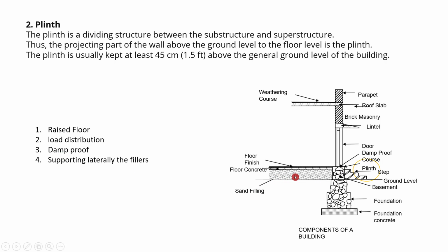It means I can have the fillers here. I told you it can be sand filling or any building waste, whatever the contractor or the builder suggests, and the plinth will provide some lateral support to these fillings.